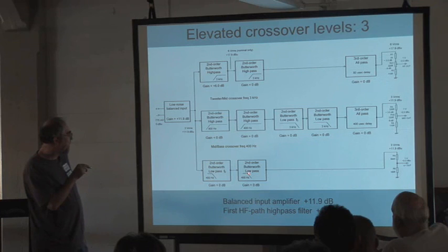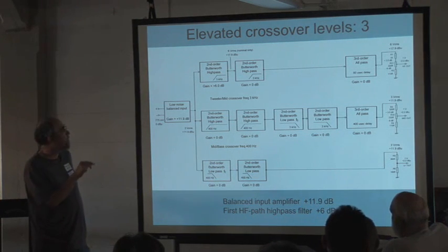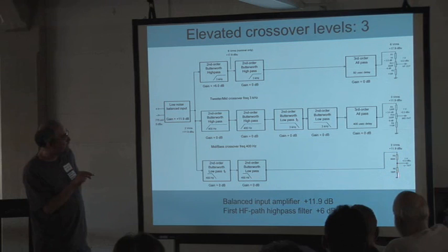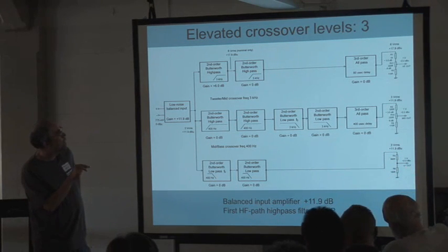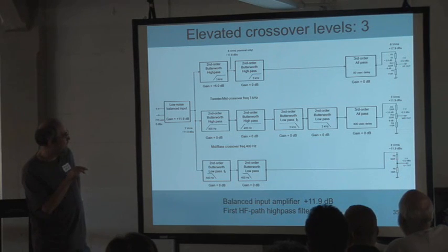2 low pass things here in the low frequency path. And there is, of course, no delay filter, because you've done your relative delays here and here, so this one goes straight through. It's the one that is not delayed. And there is a fixed attenuator there, which brings your level back down and reduces the noise, because you've got a relative tweak there and a relative tweak there, so you can simplify it there.